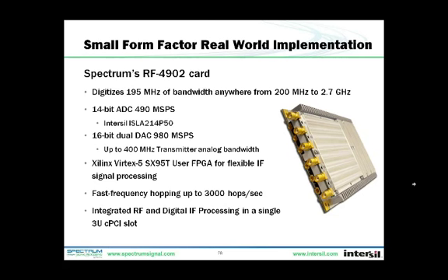It's frequency agile in the RF stage in the analog domain to enable hopping outside of the digitized bandwidth. This RF to digital baseband card fits in a 3U CompactPCI slot. So for us, integrating the RF, the ADC, and DAC, and the FPGA all onto one blade helps us to optimize the system performance, including control of noise and spurious, clock jitter, and distortion.